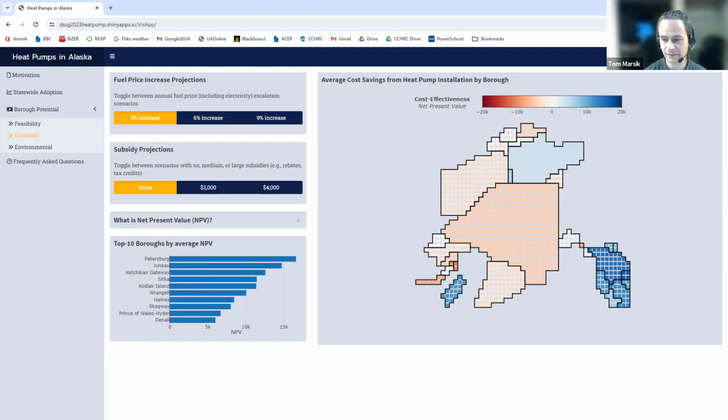It's not impossible. There are some solutions that we have been thinking of. One solution is to do an envelope retrofit at the same time. So if you can do an energy efficiency retrofit and make the building a lot more efficient at the same time, all of a sudden you need a lower temperature for your delivery fluid, and the heat pump might start actually making sense for that. So there are potential options, but again, it's not a straightforward solution.